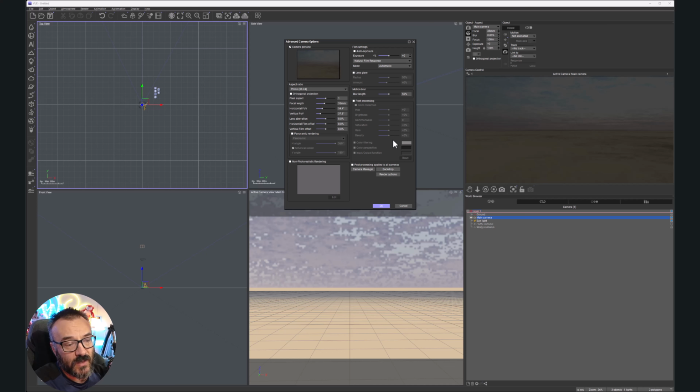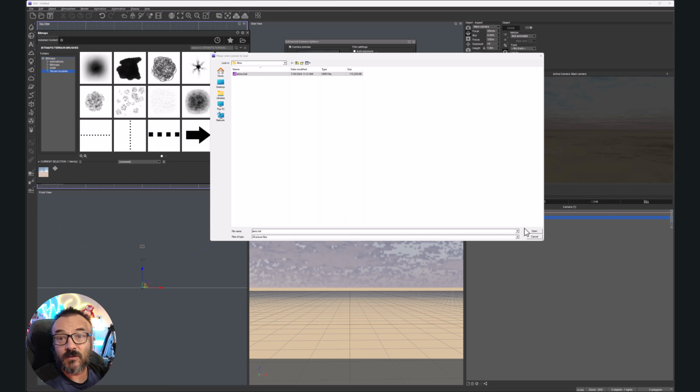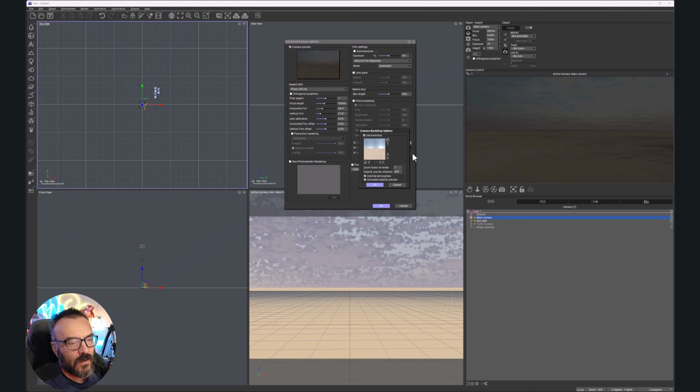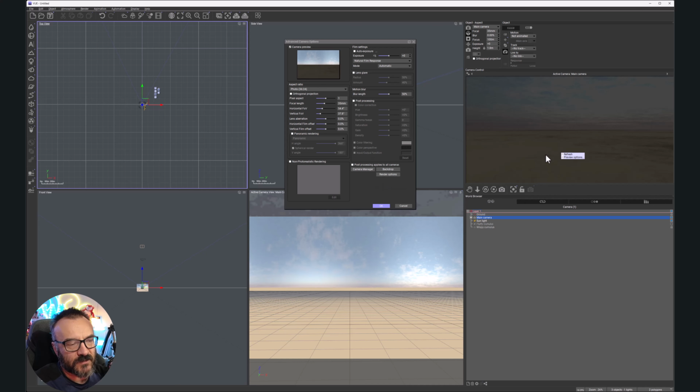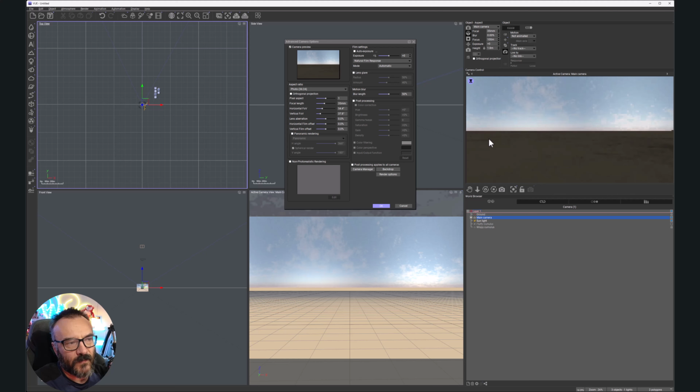But also, if you double click on a camera, inside the camera you have a backdrop. So let's click on backdrop. It will open options for us. Let's click option, use backdrop, and we'll navigate, same thing. And in some cases, it may ask you, hey, do you want to use a flat image or other things? Right here we have a zoom, OpenGL, so we can play with those. Override atmosphere settings if you need it. And you can see right here the preview, so we preloaded.